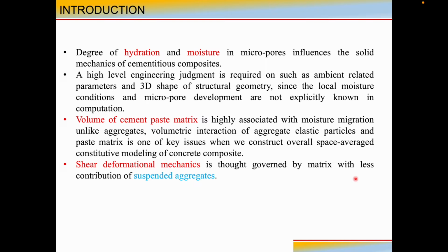Volume of cement paste matrix is highly associated with moisture migration, and unlike aggregates, volumetric interaction of aggregate elastic particles and paste matrix is one of the key issues when we construct overall space-average constitutive modeling of concrete composite. Then shear deformational mechanics is thought to be governed by the matrix with less contribution of suspended aggregates. So when we model the aggregate at a smaller scale, we consider aggregates as suspended solids or suspended material.